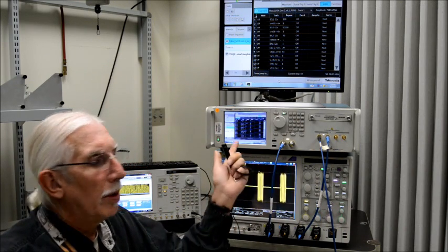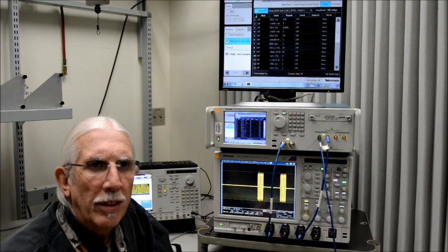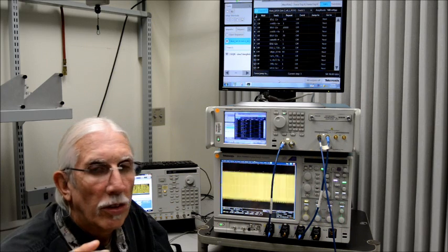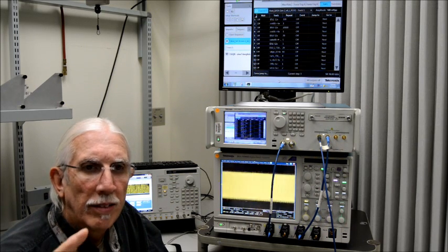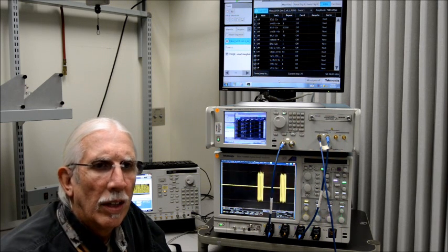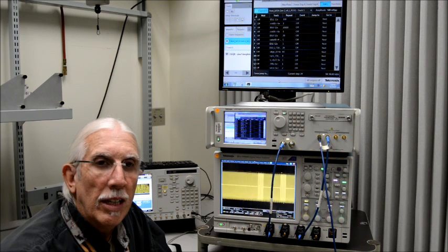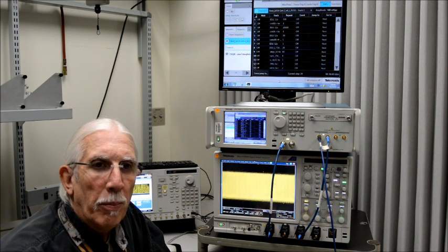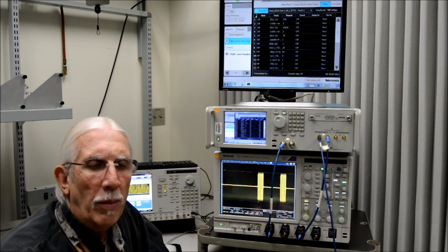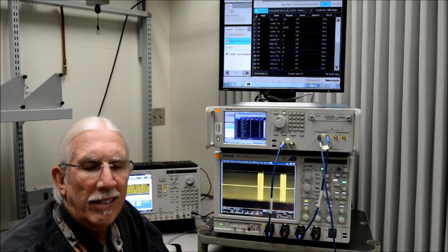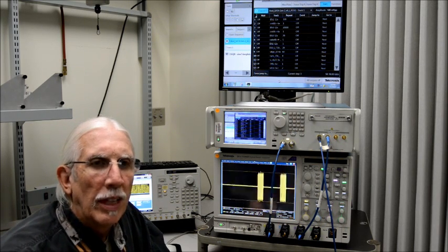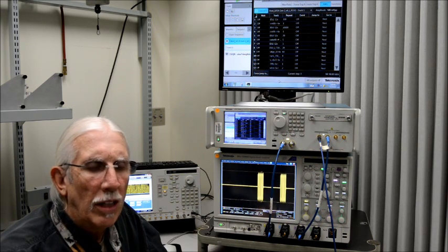Here I've loaded a little bit more complex waveforms. In this case, it's a serial data application where the first part of the sequence is used for putting the DUT, or the device, into a loopback mode, and then running waveforms that have the jitter content provided, so that you can make sure that the device works in compliance conditions, where you have to add a certain amount of jitter, ISI, and random jitter, combine it all into the waveforms, and test it to make sure you don't get any bit errors.